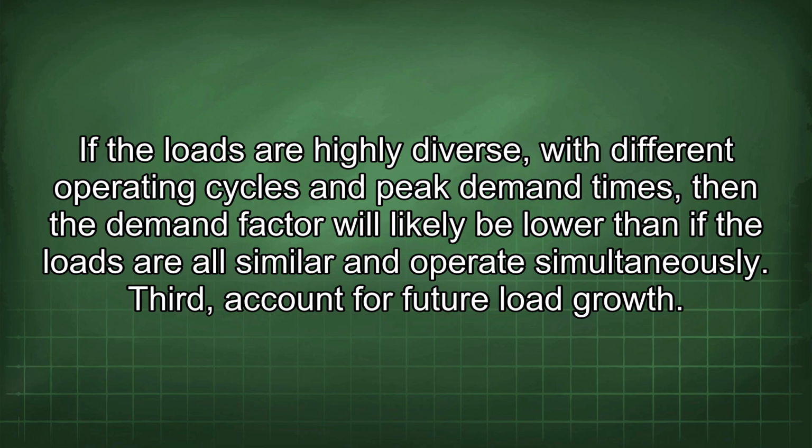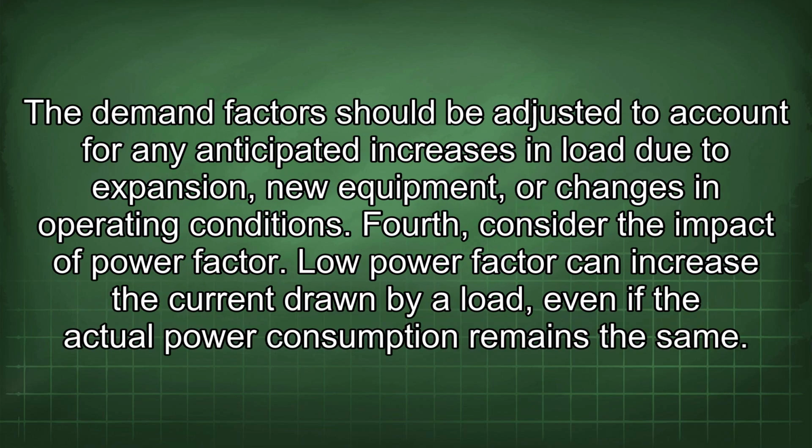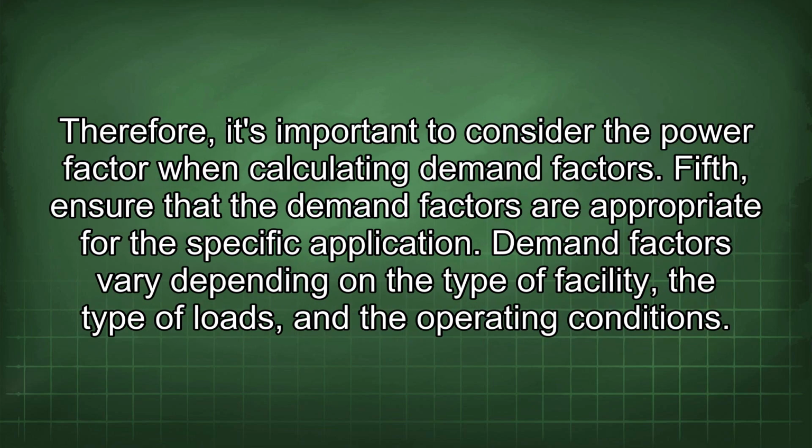Third, account for future load growth. The demand factor should be adjusted to account for any anticipated increases in load due to expansion, new equipment, or changes in operating conditions. Fourth, consider the impact of power factor. Low power factor can increase the current drawn by a load, even if the actual power consumption remains the same. Therefore, it's important to consider the power factor when calculating demand factors.